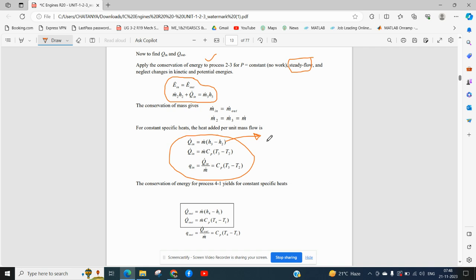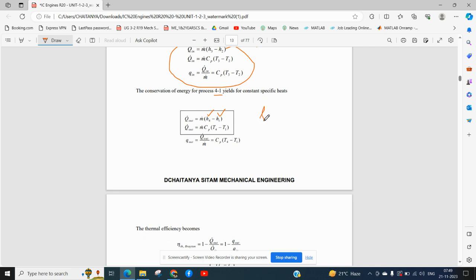After combustion the temperatures will be huge, and the enthalpy is the amount of energy stored in the gas mixture. Similarly, in the other heat exchanger from 4 to 1, there is an enthalpy difference, m Cp delta T. H4 and H1 are related, and H is a function of temperature, so we rewrite H in terms of temperature: m Cp delta T.